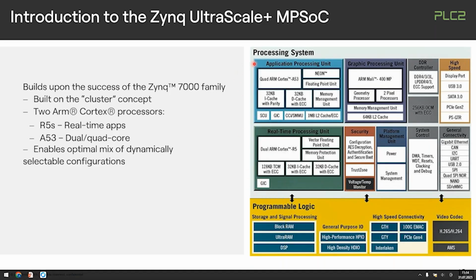You have the application processing units, like the CPUs, that are coherent processors that can be clustered together to take the same tasks, which is basically something that you would use in an operating system like Linux as an SMP, symmetric multiprocessing element. And then you have other processors accompanying this, the cluster of real-time processing units, that are there to help you with predictive latency accesses into your systems. Whatever you need to control in a certain time frame would need at least to be countable. So that's the kind of approach that you take in here.